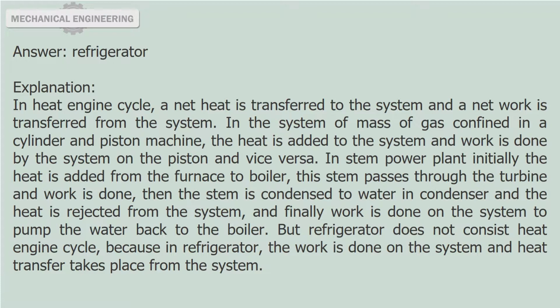In steam power plant, initially the heat is added from the furnace to the boiler, this steam passes through the turbine and work is done, then the steam is condensed to water in the condenser and the heat is rejected from the system, and finally work is done on the system to pump the water back to the boiler. But refrigerator does not consist of heat engine cycle, because in refrigerator, the work is done on the system and heat transfer takes place from the system.